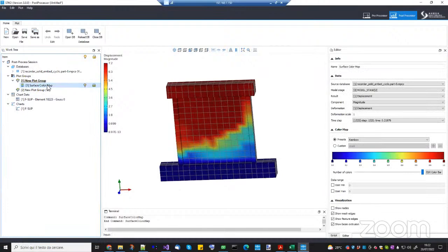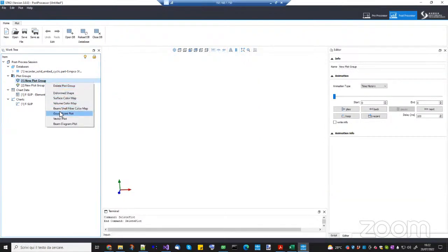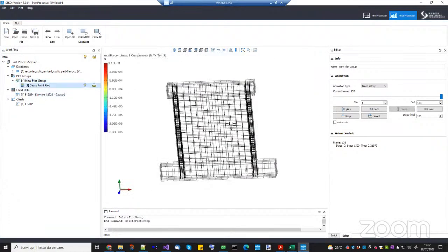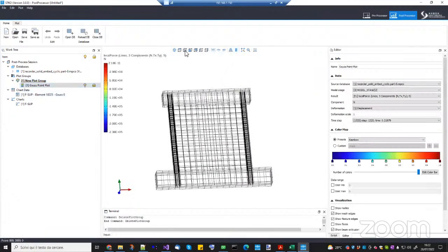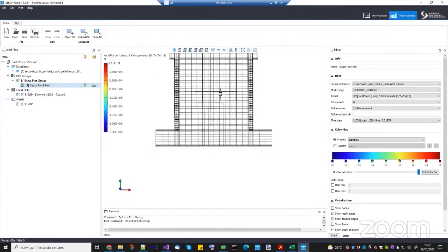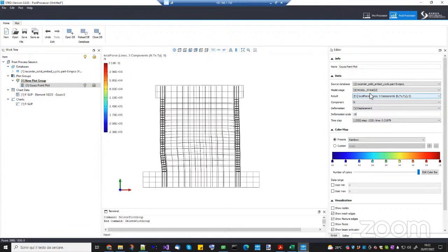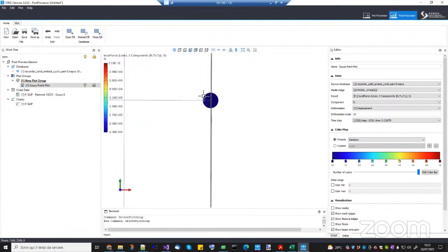Yeah, I didn't have time to show everything, but I want to show the Gauss point. If I show the Gauss point, in this case I also ask for local force, and the local force for the contact springs gives me 3 components: the normal force component and the 2 tangential forces, because it is a frictional contact.